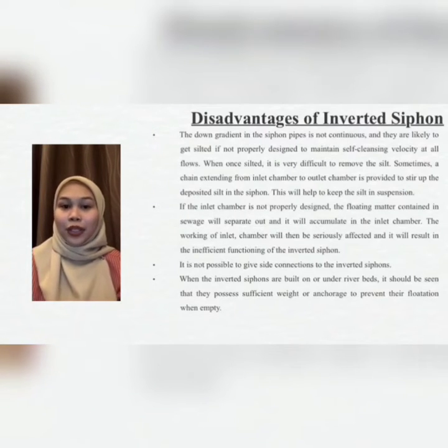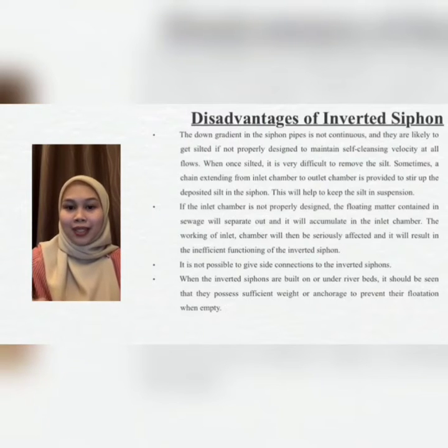It is not possible to give side connections to the inverted siphon when the inverted siphons are built on or under riverbeds. It should be seen that they possess sufficient weight and are encased to prevent floating when empty.